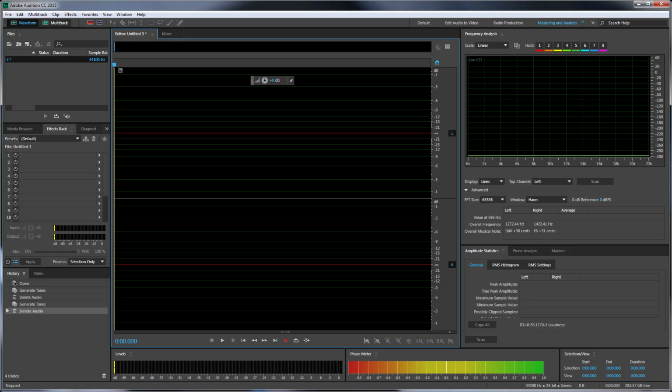31,250. But of course, it's interlaced, so it's not scanning all 625 lines each time. It's doing half of that, so divide by 2, and that gives you 15,625 hertz, so 15.625 kilohertz. That is the frequency of a squeal on a television.